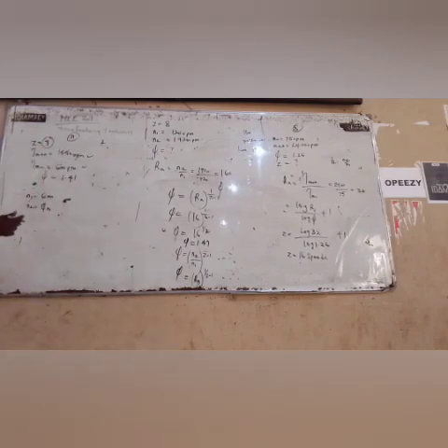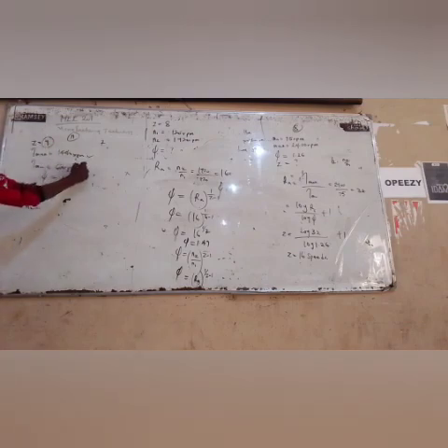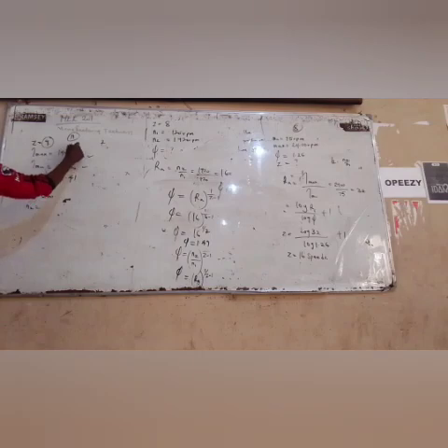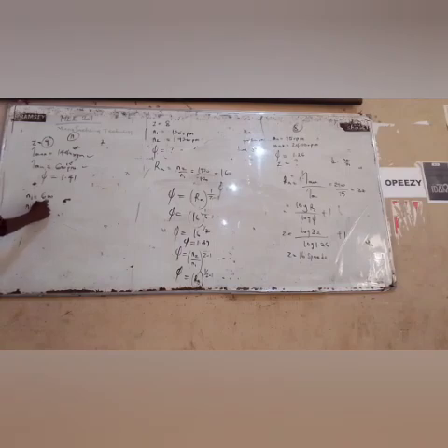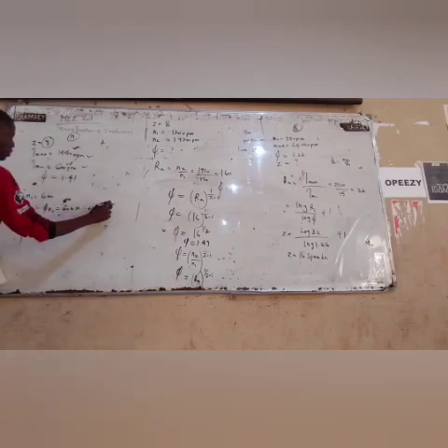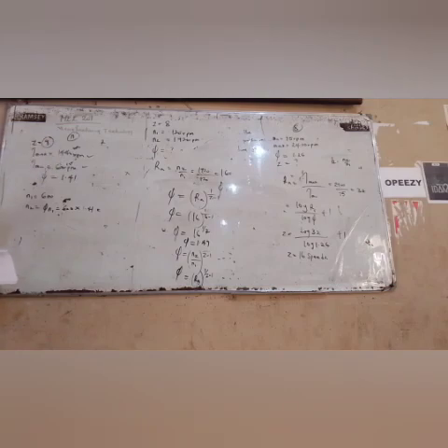Let me even solve it. For us, N2, you know it's 9, so we are going to 9. This is the first one, and this is the 9th one. So there are 7 speeds in between. If you want to get the 7 speeds, this is the first one. The second one will be N2, this one, N1, 600 times 1.41. Put it there. If you want to get the second one, anything you get here times the progression ratio, till you get to the last one, and your final one will be the 9th one.